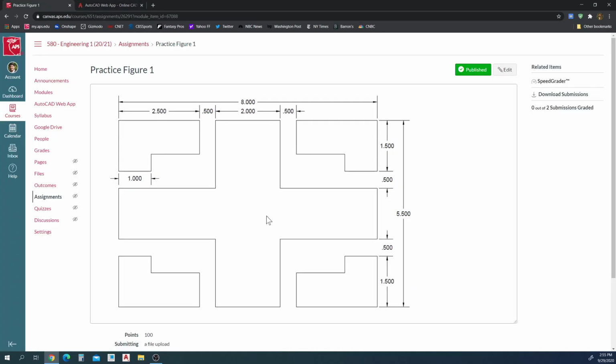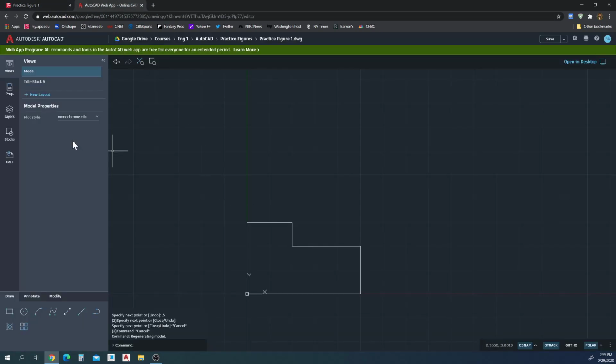Okay, so gap here of 0.5, and then we're going to start a line, draw 0.75, half of whatever this line is, add these up, subtract by 5.5, 1.5, so 0.75. All right, line, snap, pan up. You get that following green extension line. That means we want a certain distance away. How far away? 0.5 inches away. There it is. Good. And then we want the actual line to be 0.75. Okay.